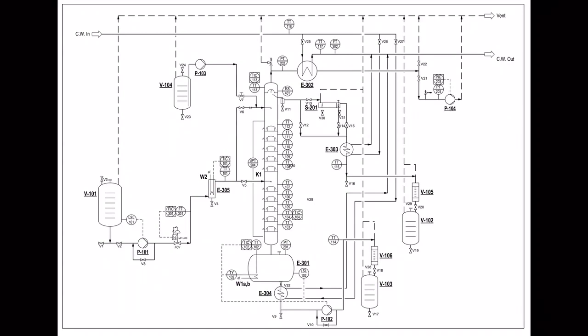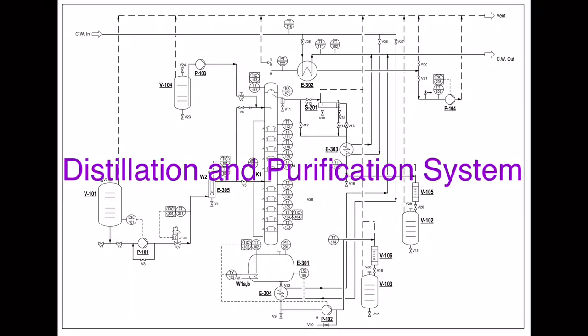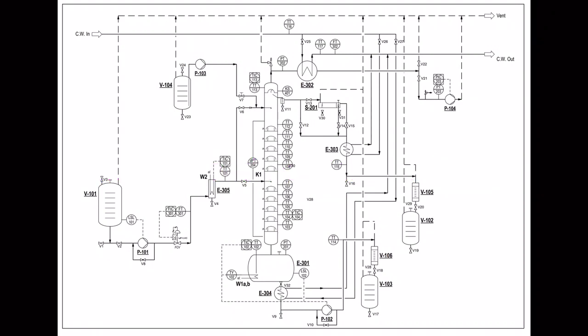So in this screencast, I will show you the E-lab on the continuous distillation column system. Before we proceed with the experiment procedure, we have to perform the general startup procedure. First thing first, you have to make sure all valves in this distillation column system are initially closed.